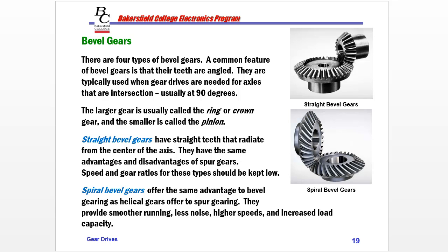And then if you're not going to be using the vehicle for that, well, maybe you would get a lower ratio, which would give you less torque down at the slow RPMs, but it gives you a faster or higher top end without your motor working as hard.